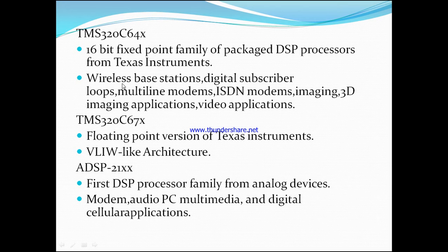This is an extension to the Texas Instruments line. This processor family targets high performance applications like wireless base stations, digital subscriber loop, multi-line modems, ISDN modems, imaging, 3D imaging applications and video applications. Next one, the TMS320C67X family, is a floating point version from Texas Instruments. It is also based on the VLIW architecture.